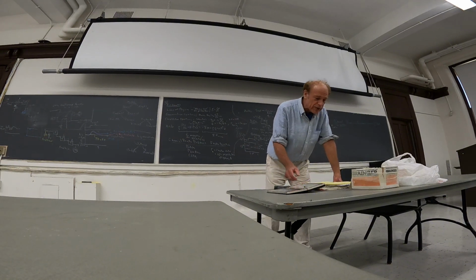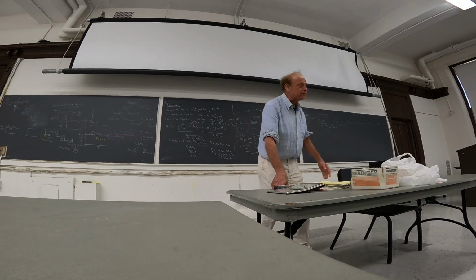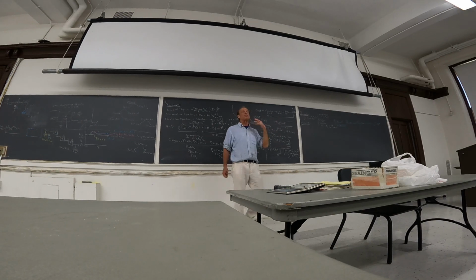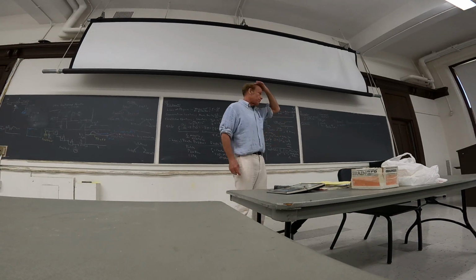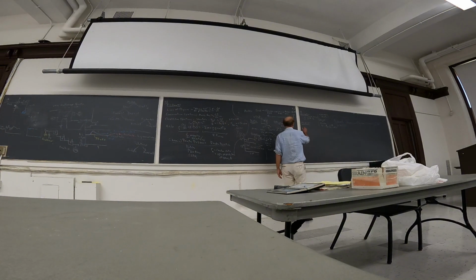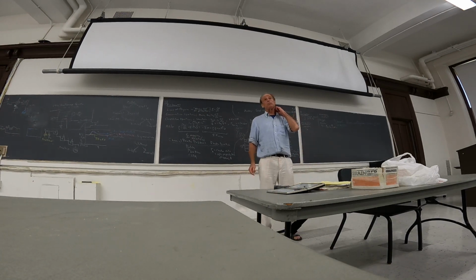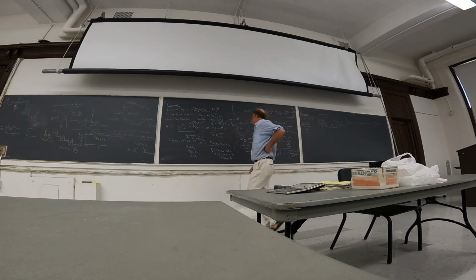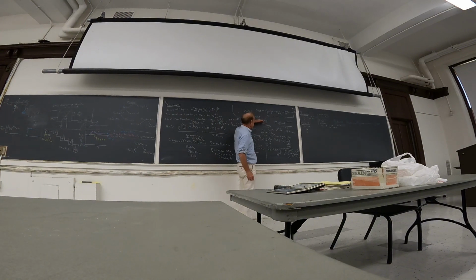Okay, so now we need to determine the variables here. If I have a system, if the volume is fixed, so what are the variables here? Let's look at this particular problem. What are the degrees of freedom? The variables are the concentration of A and possibly the volume of the reactor. So, who said that the reactor is full? Maybe the reactor is not full and stuff comes out.